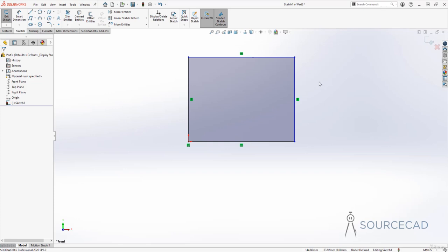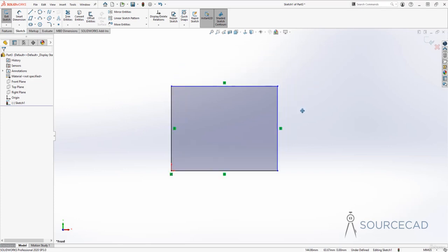But before we do that, I want to draw your attention towards this thing. Right now this drawing is underdefined or not fully constrained, and when it's like that, SolidWorks will show you here on the status bar the status of your line. So it is underdefined. Actually, we have a couple of lines here, so it will show you the status of your geometry. Now let's add some dimensions, and for that I'll go to this Smart Dimension tool.